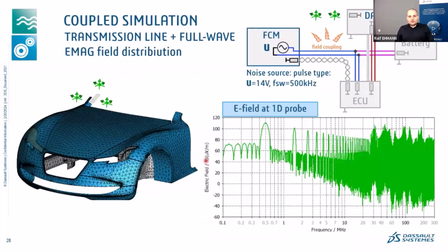And this slide is oriented to any simulation designer who is, for example, still waiting for another engineer or designer to deliver a specific model of the antenna, which may happen. CST, since the beginning of time, has had the 1D probes, which were already presented today many times, which can get the field values around the location where the antenna will be. So we can very quickly position those probes and get the field information.